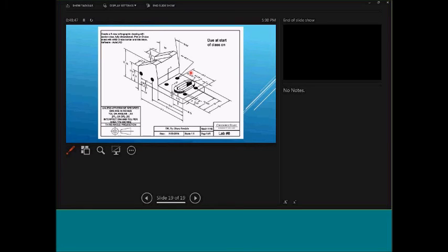Well, usually what I've tried to do in some of my labs is actually give them the orthographics and then ask them to model the 3D model to see if they're properly interpreting the orthographic views. Right. Because like I said, if we build the 3D model, the program gives us the orthographic views pretty much, and it becomes a dimensioning exercise after that.